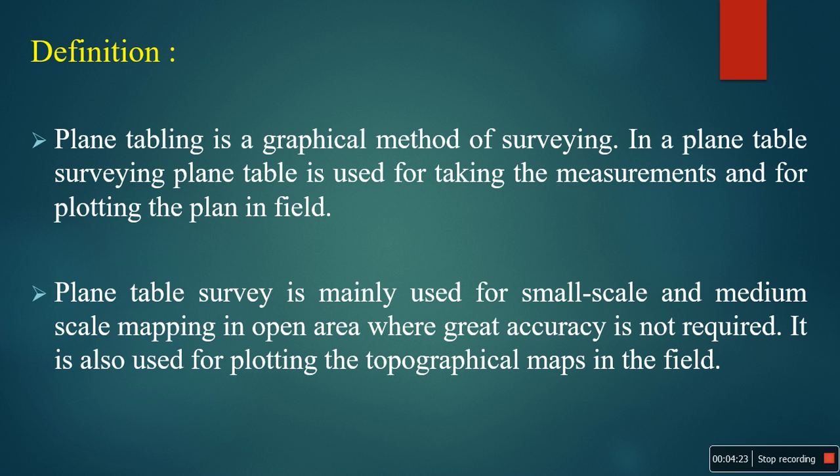Generally, the plane table is used for small scale or medium scale mapping in an open area. It does not have great accuracy compared to the other methods. If it is a smaller area, you can use it even where setting up the plane table is difficult. If a huge area is considered for surveying, plane table surveying is tedious and not of great accuracy compared to other surveying methods. So this is the introduction to plane table surveying.